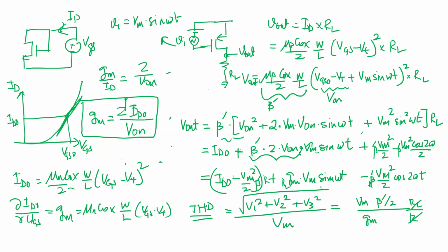But your supply is only 1.8 volts. So there's no way you can bias it. That's why the current sources are called active loads. These active loads actually decouple your DC biasing from your AC gain and your impedances. Make sense?